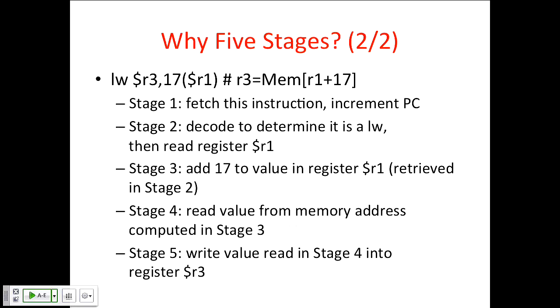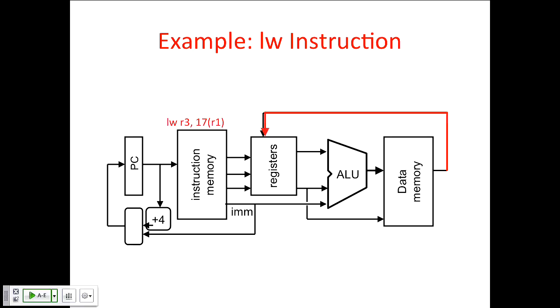And this is just going through the load instruction, how that executes, just to show you that. So, it finishes up with this. It's a broken animation. It goes through, loads the address, calculates the address, sends it to memory, gets the result, and writes it back to the register file. Okay, so load is using all 5 stages of this execution.